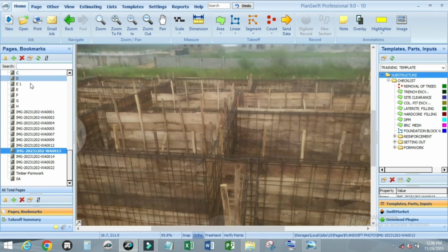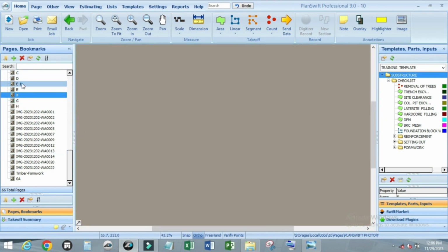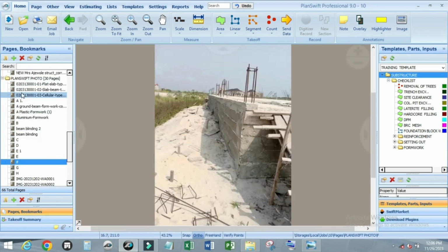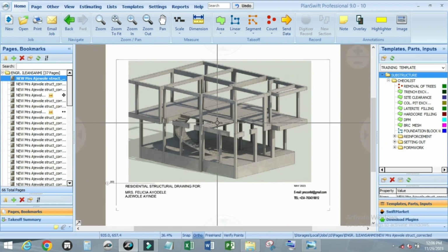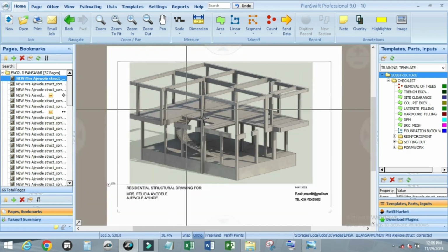You can't just come to any site and decide by yourself, as a site engineer or contractor, that you want to make use of a raft foundation. The type of foundation will be determined by the structural engineer based on the soil test, which enables them to determine the type of foundation to be used for the construction.